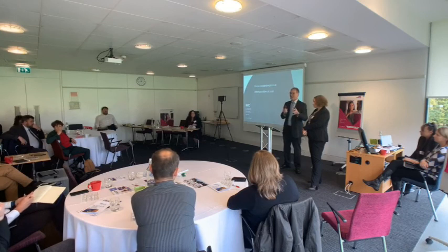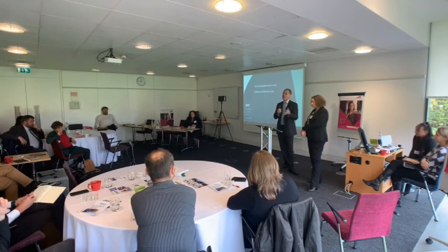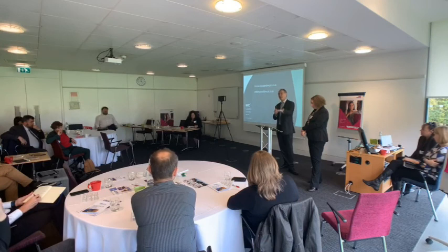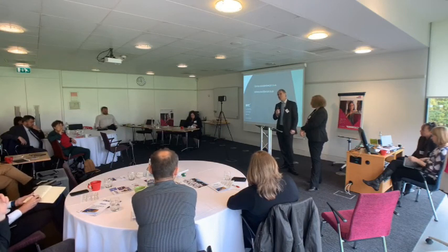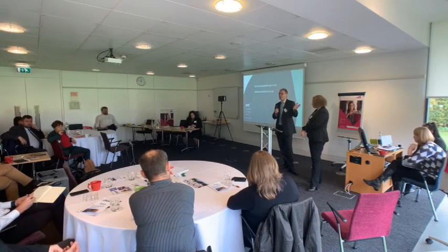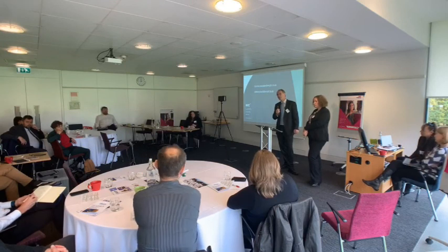We're pleased to say that we're able to at least give you an indication of the size, so that should be helpful. And then if you can indicate whether it's at a joint or in the barrel of the pipe, clearly if it's in the barrel of the pipe, act now. If it's at a joint and it's small, certainly in a lead run joint, then typically we would advise to monitor it, depending on where it is. If it's in the middle of a field, perhaps you want to go and mend it. But if it's in a very difficult area, you might just want to monitor it.